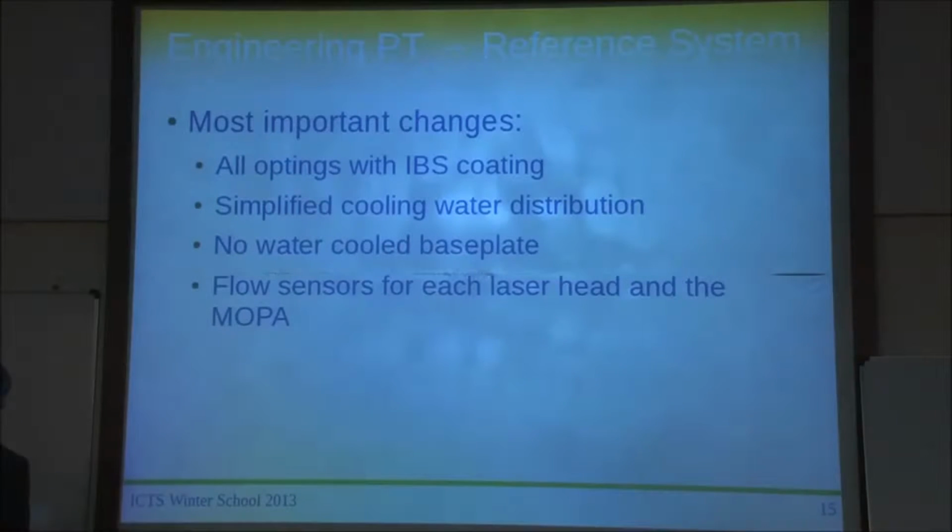So it was already hard to machine it, but we also added some water device, because we thought maybe we want to have this base plate at a stable temperature, and we need to cool it at least a little bit. But that turned out not to be necessary. The temperature is rather stable even without the water cooling, so that saves some costs.